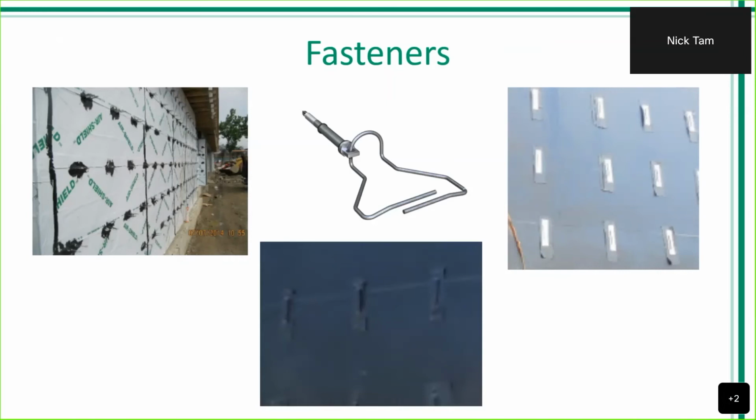And then there are going to be some penetrations where spraying over the top of it may not be the best option. Look at the strips here. Well, if we spray over the top of it, more than likely we're going to miss somewhere behind it, and that becomes an issue with potential areas where we may not see gaps in the membrane. So definitely consider what type of ties are being used in deciding if we are going to spray over or if we're going to install after and have some way to gasket it.